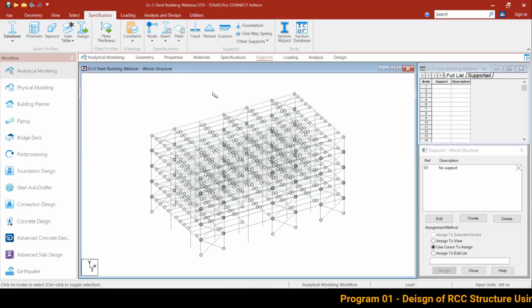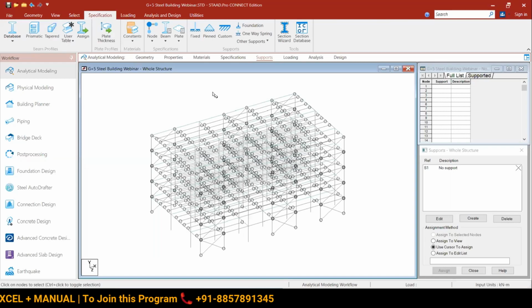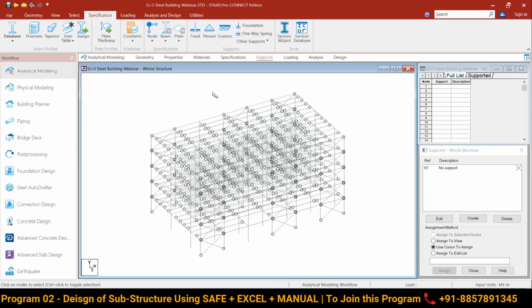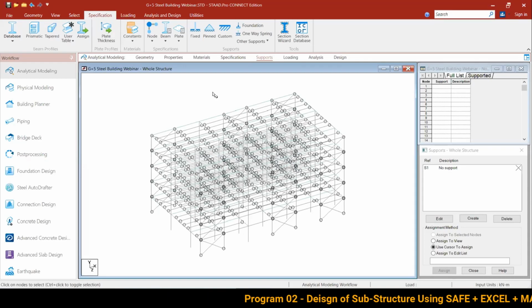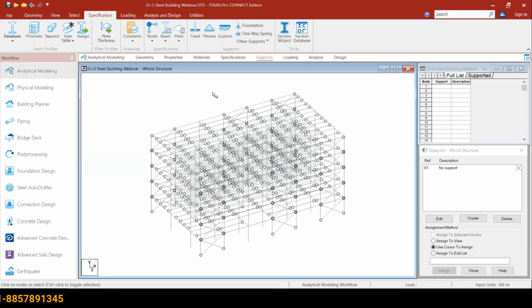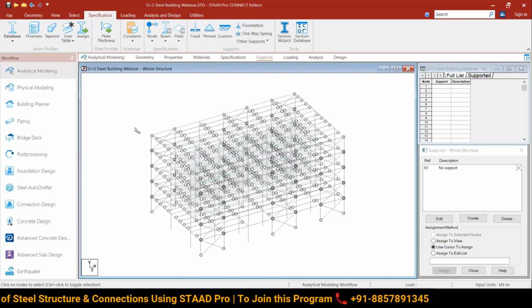It's not like in Staad we are modeling a shear connection and practically on site we are just giving them a random connection. For connections also we have proper drawings where we define this is my moment connection which will take a particular kind of moment and particular kind of shear, and this is my shear connection which won't take any moment and will only take shear force, to a certain extent. Based on that we decide the number of bolts required, the size of bolts required. So the design of connections is also one of the important parts of structural analysis.